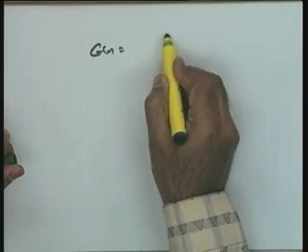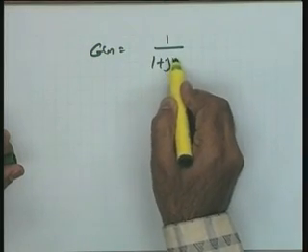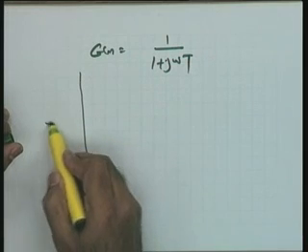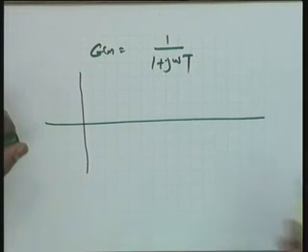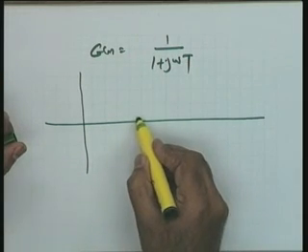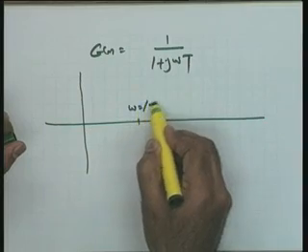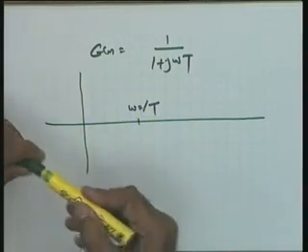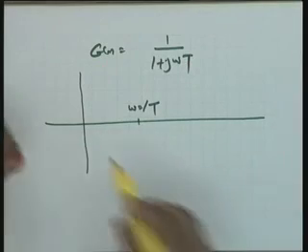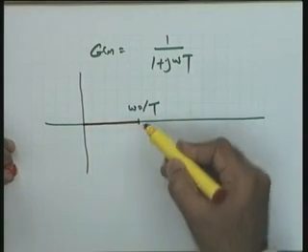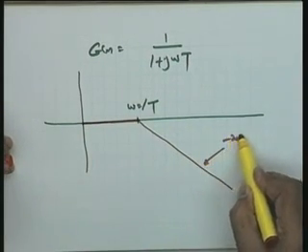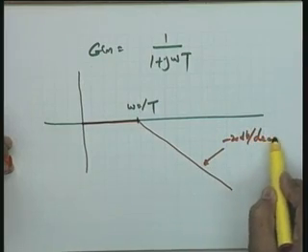I sum up now. The factor Gs is equal to 1 over 1 plus j omega t. This is my factor, and the method is the following: magnitude plot. I take omega is equal to 1 over t as the corner frequency, okay, and I make this line and this line a line of minus 20 dBs per decade.